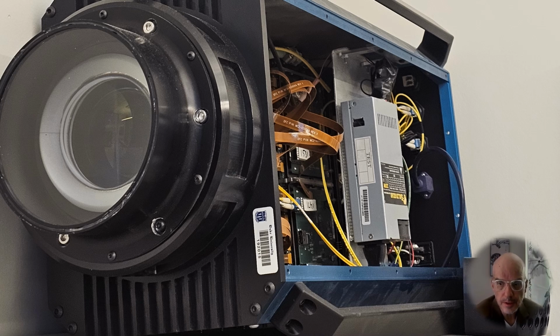This is an HG camera, half gigapixel, built under the DARPA AWARE program by my group at Duke University. The camera has a spherical lens over here on the left, and then behind it, each of these ribbons connects to a 14 megapixel micro camera. So as a whole, the camera has 64 of those, and it puts out somewhere around half gigapixel per frame, and at 20 frames per second, somewhere around 10 gigapixels per second of data.